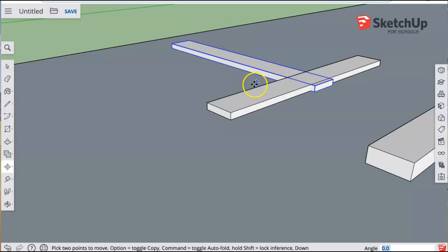That's 90 degrees. Now, to rotate this piece, I'm going to do it using a different tool. I'm clicking on the object, I come over here, and I use the rotate tool. Now, again, I need to make sure that I grab the correct surface. I want to be on the blue axis here, not on a red side or a green side. I'm going to get my blue corner, click on it, and release. That's a pivot point.